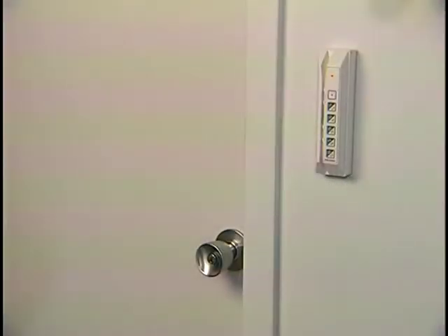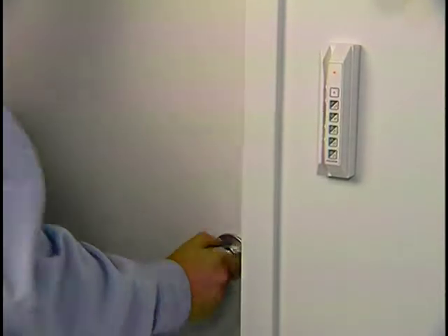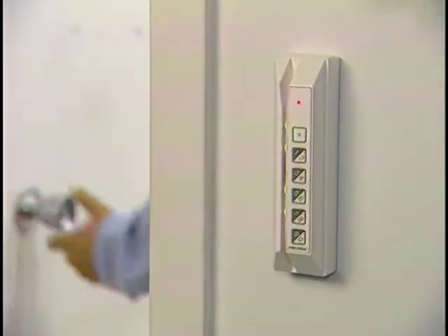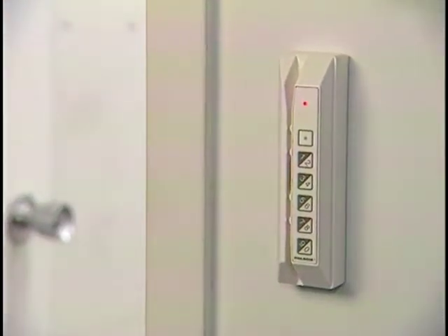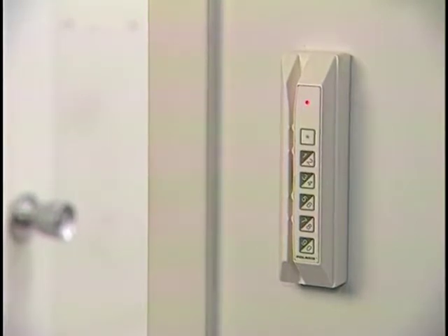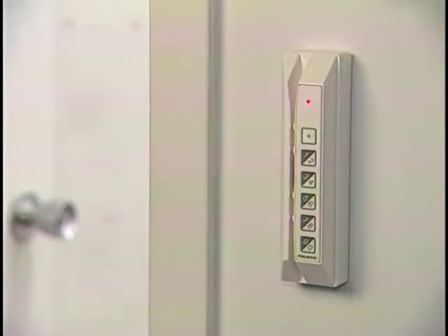If a door is left open for half of the door open time, the buzzer in the reader will begin to beep once every second to alert the user that the door should be closed. If the door is left open for more than the door open time, the door will be considered open too long. This event will always be logged to the event buffer of the panel, and the buzzer in the reader will always sound.